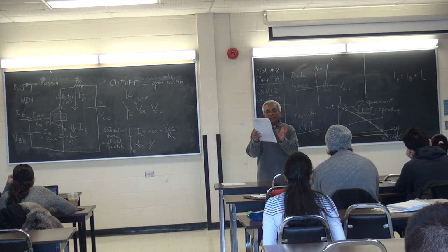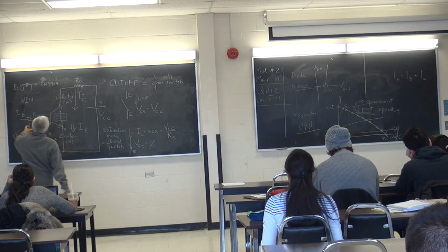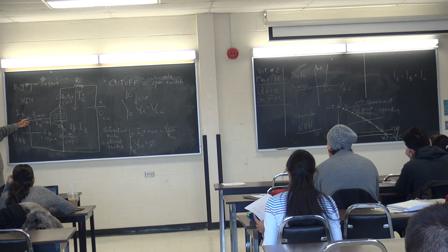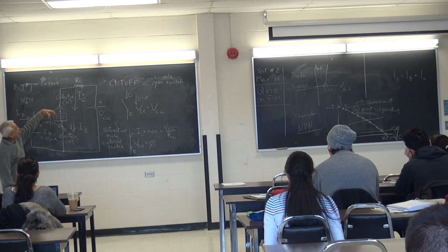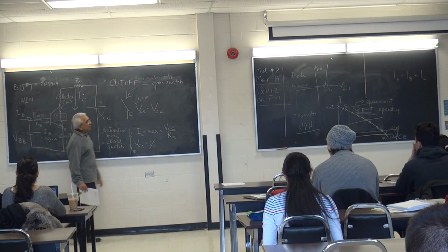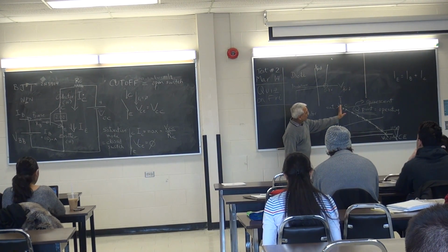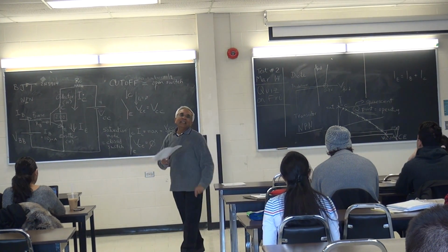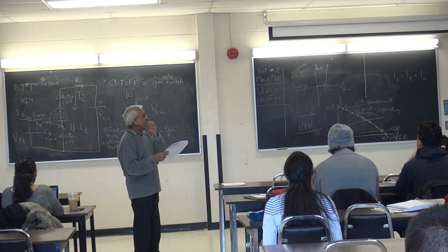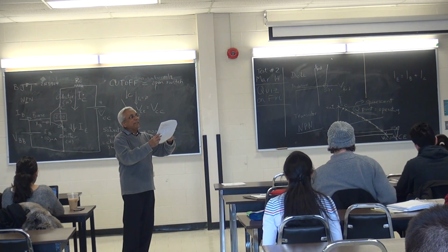So can you appreciate the fact that if I put a large base current, does that mean that I've opened up my tap a lot? So opening up the tap a lot means there's a lot of base current flowing, which is causing a lot of collector current, and that means that I'm going close to saturation, and therefore the transistor is going to act more like a closed switch. That's, in a nutshell, how a transistor behaves. Okay? So that's my page 9.